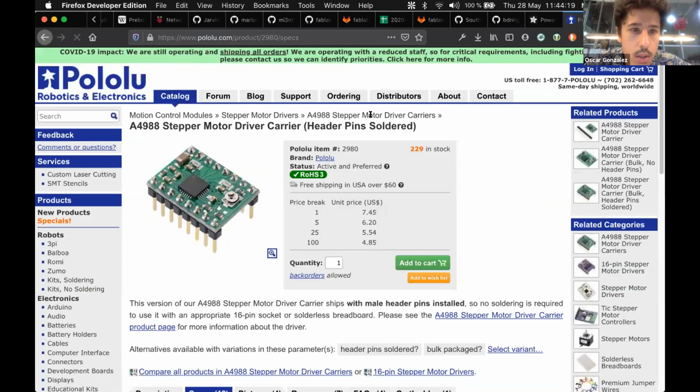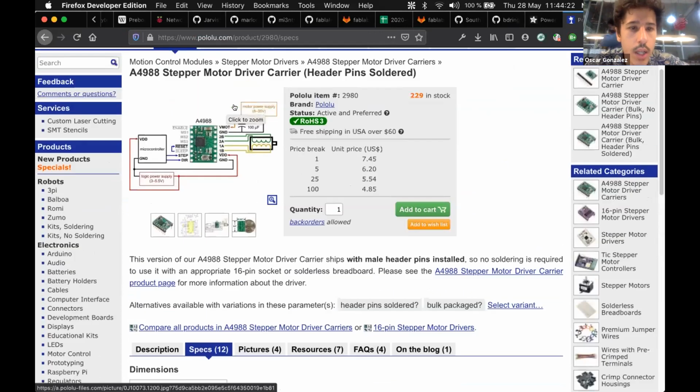There is one thing that you have to take into account: if you see in the wiring here, the outputs that you will have are directly connected to the header connector that we have in there. And there is also a configuration for micro stepping. Okay. And these things are generally quite standard. So if you want to use another one, like a DVF, this is also a compatible stepper driver, and probably many other stepper drivers will also be available for you to use.